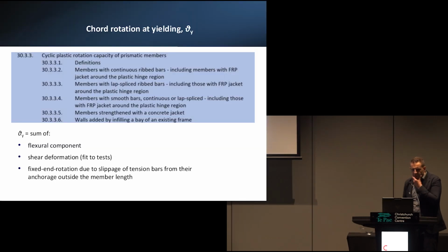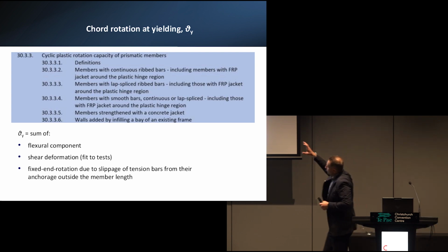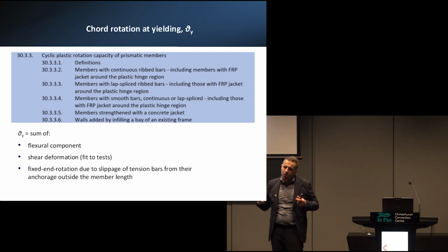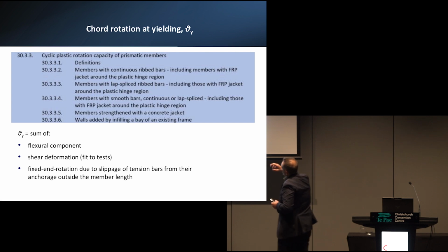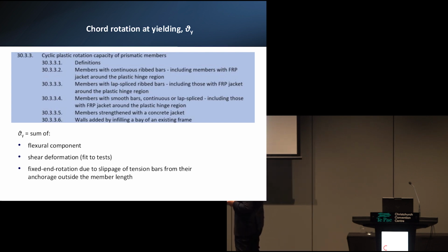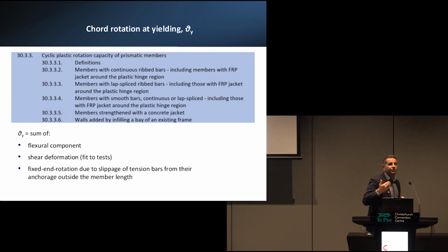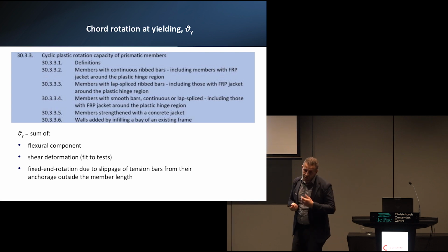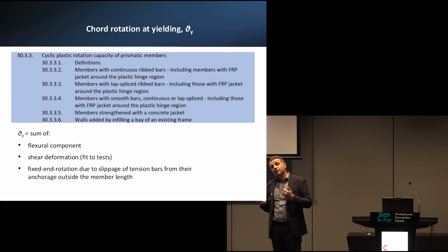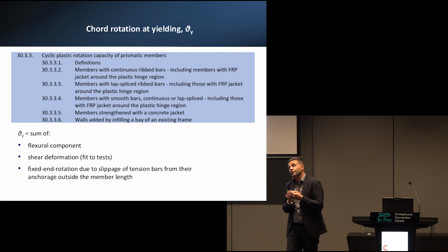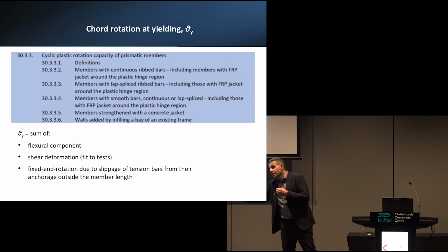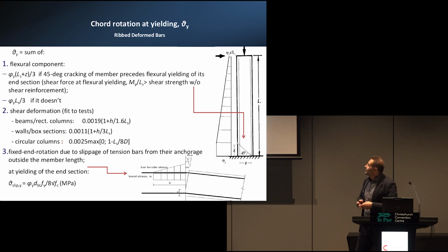In general, the section, the most important part, which is related to the rotational chord, I would say, in general, you have the three main components: the flexural, the shear deformation, and the fixed end rotation in case you have slippage. And that is very important, especially if you have an existing structure where you may expect that the development length has not been properly analyzed, or especially if the structure was designed without seismic codes. Therefore, you may have that contribution. It's quite important because it's increasing the deformability of your structure. And these are the three components.